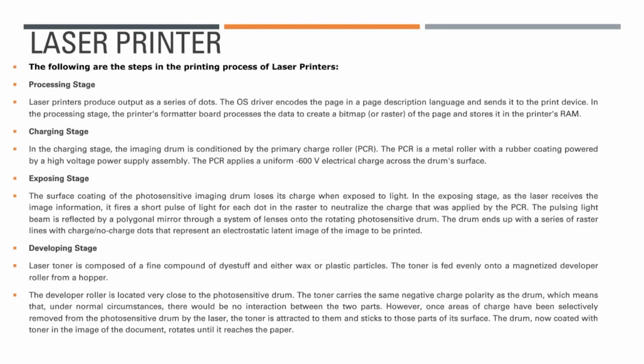Developing stage. Laser toner is composed of a fine compound of dye stuff and either wax or plastic particles. The toner is fed evenly onto a magnetized developer roller from a hopper. The developer roller is located very close to the photosensitive drum. The toner carries the same negative charge polarity as the drum, which means that, under normal circumstances, there would be no interaction between the two parts.